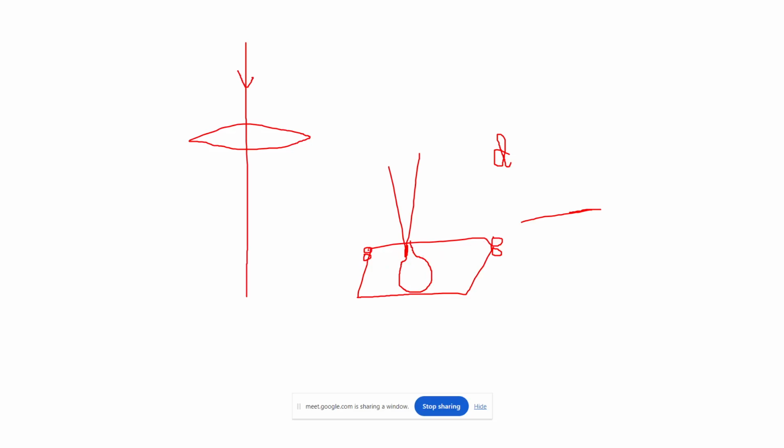scanning on the specimen, and after the scanning it interacts with the specimen, and the electrons which come out from this specimen go out. Depending upon the detectors which you are using, the secondary electron detector is placed over here. There is also a backscattered electron detector, which is a donut-shaped detector placed around the optic axis only. It is hollow.